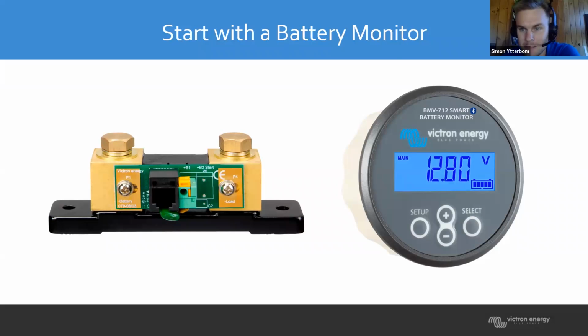We know that the battery is still fully charged, even if it's showing a low voltage for that short period of time. So voltage is only a measure of the load put on a certain size of a battery. That's why a quality battery monitor is important to have, so you can truly see what's going on with your battery and when you need to recharge and when you can use power because it's fully charged, and so on.